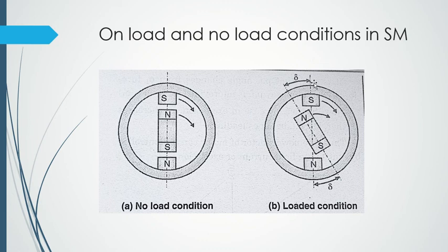Now what will be the resultant voltage? Firstly, let's talk about no load condition. What will the resultant voltage be at no load conditions? As there is no load connected, the resultant voltage will be the supply voltage minus my EMF, V minus EB. Since there is no load connected, the supply voltage will be equal to my EMF. So the resultant voltage will be zero, and as there is no voltage produced, there will be no current flowing in the circuit. Pretty simple.